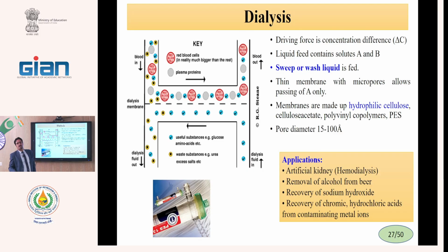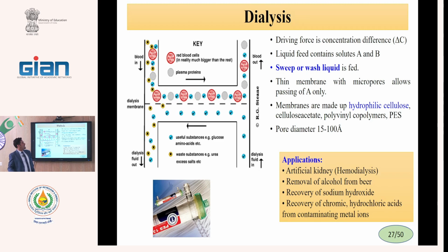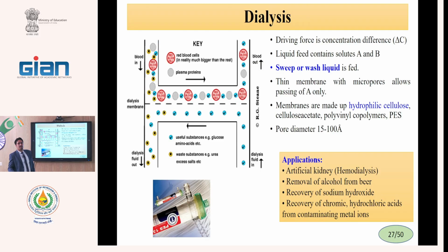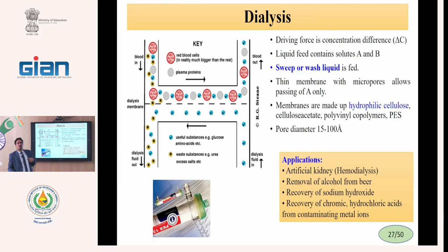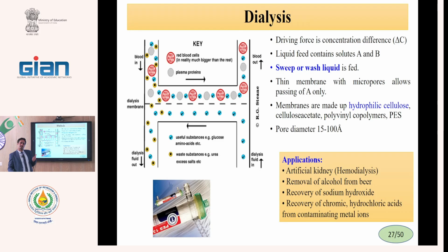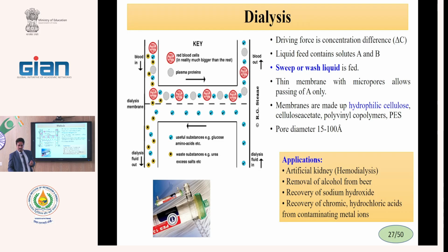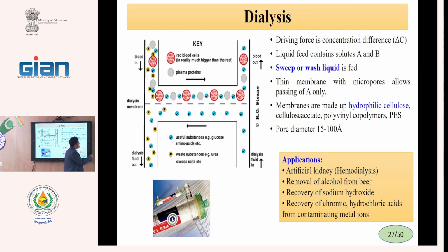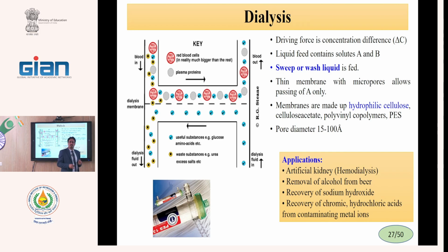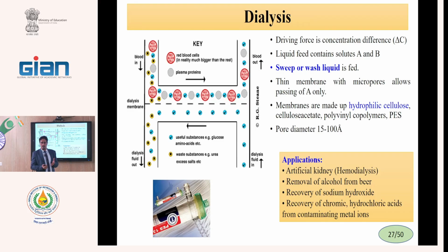The other process is dialysis. In MF, UF, NF, RO, most of gas separation and pervaporation, the driving force is pressure difference, delta P. In a dialysis membrane, the driving force is concentration difference, delta C. This membrane is similar to an ultrafiltration membrane.